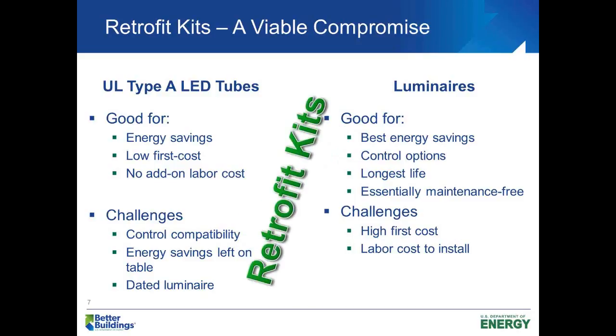Enter retrofit kits. Retrofit kits essentially use the shell of the existing luminaire, gutting the lamps and much of the existing electronics, with new light engines and drivers in place of the ballast. Retrofit kits can provide greater energy savings and controllability than plug-and-play LED tubes.